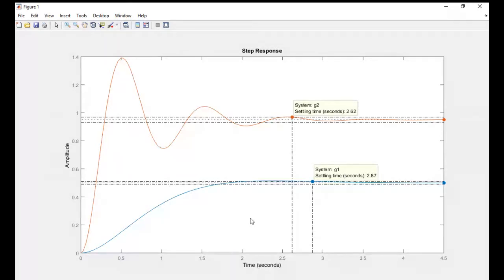Don't lose your point. I just want to clarify something before we move on. What we're seeing here is a slight reduction in the settling time, because we move from K equal 2 to K equal 40, and in my opinion that's a fair enough increase in the gain. But look at the settling time; it moved from 2.87 to 2.6. It's a very small change. There's nothing significant happening in that. So the settling time does not change significantly due to the increase in K.